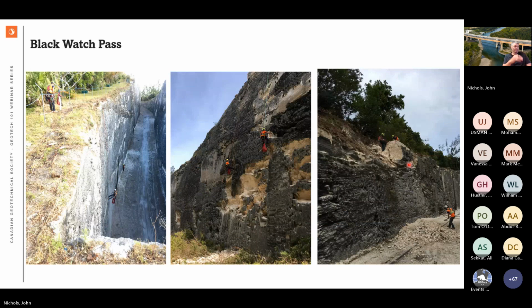So you can see the first thing we did, in this photo, was the tree removal. It's important because the roots that grow in these cracks over time, there's weathering, and then you get some wind. This forces on those trees, and root jacking, we call it, can really cause rockfall to occur. In northern climates, you get frost jacking, which is where water gets in and, as it starts to frost and get hot and cold, the ice expands in these cracks, but that's not the case here.